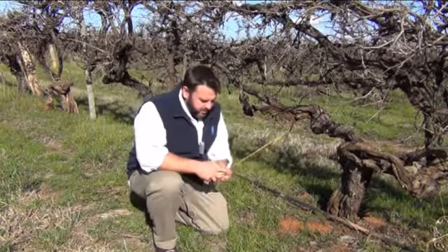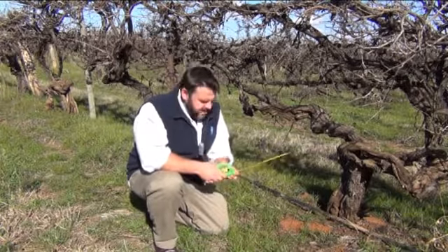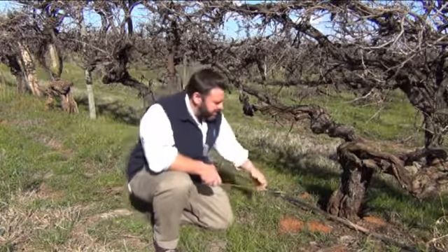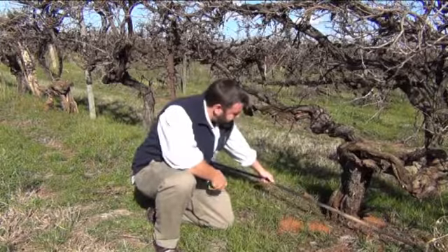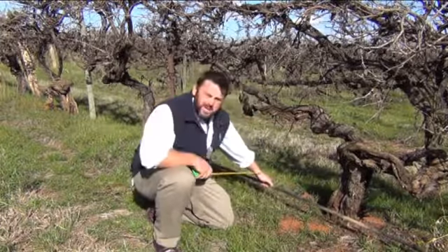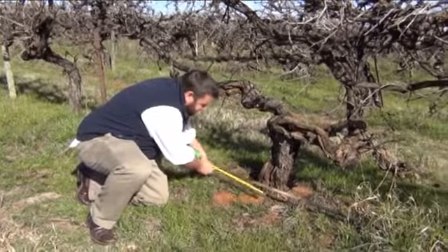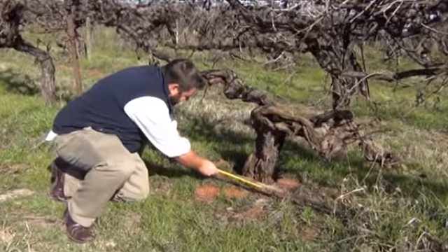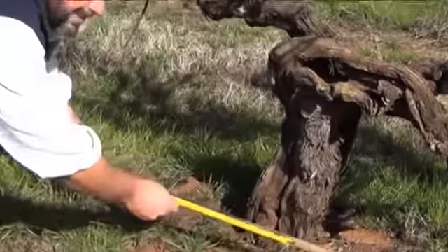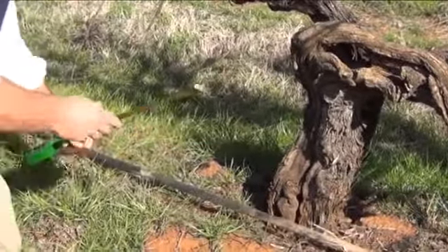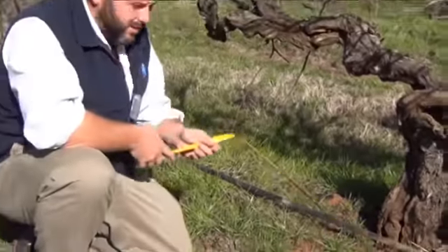Okay, so the first tool you need in order to collect the information is a simple tape measure. What we want to do is to measure the spacing between our drip emitters, which we can use to work out our application rate. So you can see for these particular emitters, they're at a 60 centimetre spacing. So we'll record that information, which will be entered online within our notebook.